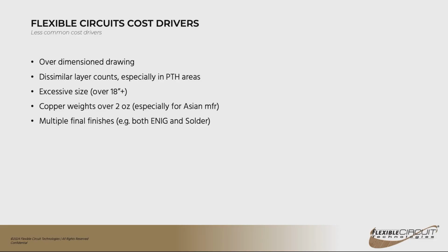Is there any consideration in using fine pitch or ultra fine pitch components on flex circuits? There wouldn't be any additional concerns other than just the fact that if your circuit is fairly large, those fine features are going to be more difficult for us to define than it would be for a rigid PCB manufacturer.